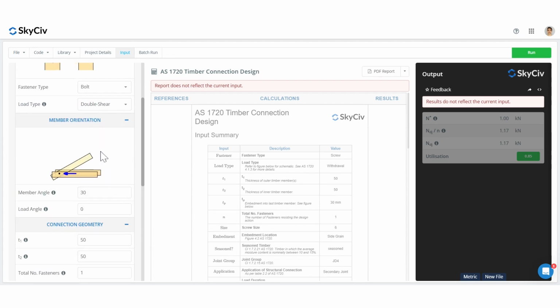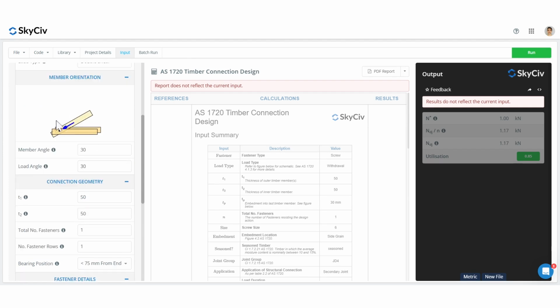The design example also tells us that the force we're going to be using is the force inside this top chord. So we're going to incline the load to be in the same direction as this member here. And we can see in this design example, this is exactly what our truss looks like. And of course, we have some supports at the bottom here, but for the purpose of our calculation, the only force we really need is the force in this member, which gets applied to this bolt, and it gets applied to this member, but we don't really need to worry too much about how these forces are moving about. We just need to know this force we want to apply on the connection here.